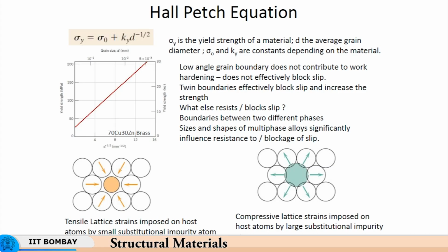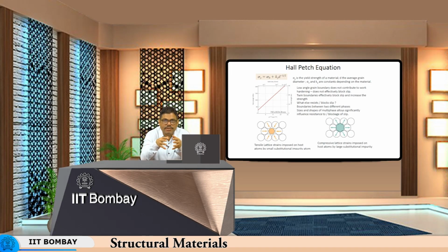So when you have a certain amount of these materials dissolved in steel, for example, behaving as interstitials in steel, then they will generate a significant amount of lattice strain due to which the resistance to deformation is increased tremendously, and ductility comes down very rapidly.